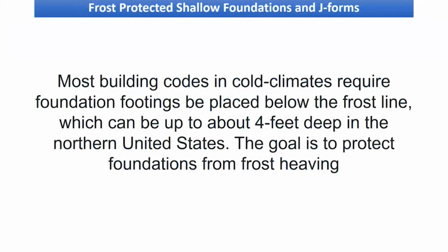Many codes permit foundations to lie above the frost line as long as they're protected from frost. However, approval depends on local code officials and may require special engineering. So they do allow for shallow footing systems, and that's where a lot of the time the question gets asked when we're talking about J-forms: do we have to dig down to frost if we're using J-forms? That's part of what we're going to be going through in this presentation.